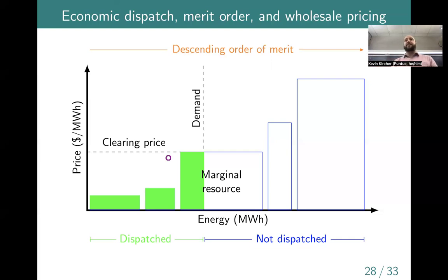Question? So you're incentivized to create cheaper power because you can make more margin if you make the clearing price either way. Yeah, so the suggestion is that you're incentivized to produce lower cost power, and I think that is right. There's one incentive, which is that you want to get dispatched. You want to be low in the merit order, or low in the stack, so that you're likely to actually run. If your power plant produces really expensive power, you never get turned on, and you're not going to make much money. So that's one reason you want to make a low offer.